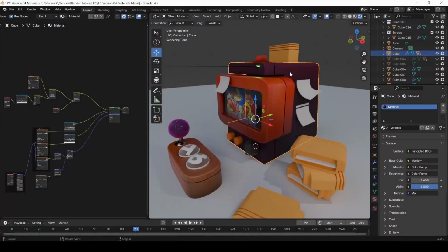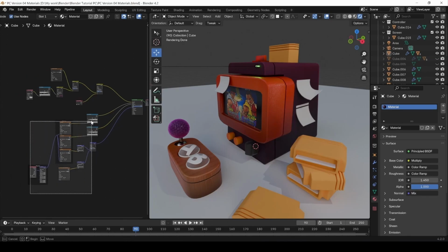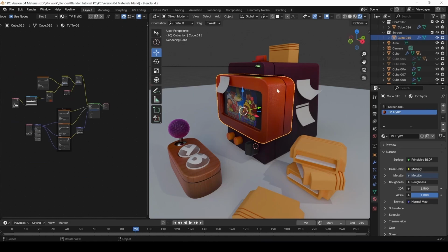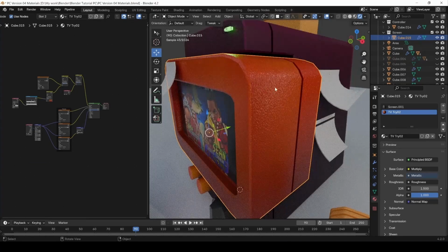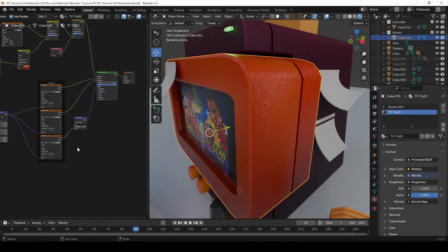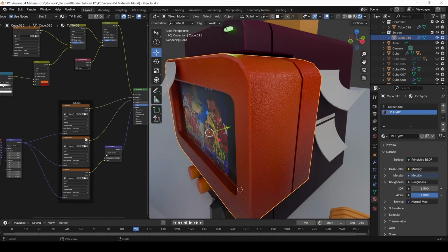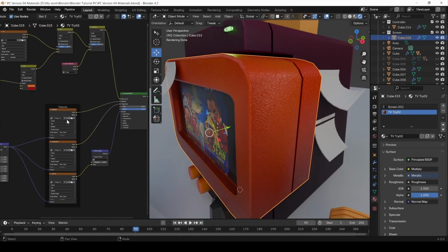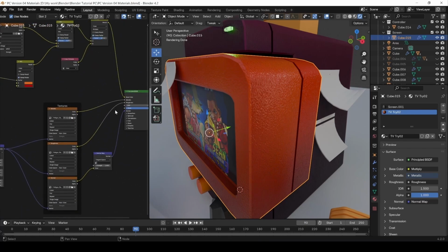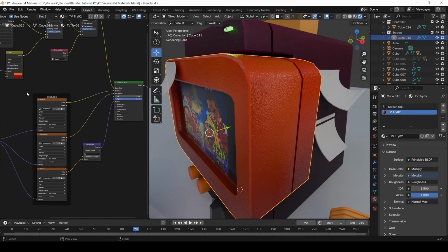So now we finished this, and what I decided to do is basically take all these materials, without this bottom one, I just copied them with Control C and took them to the others, to just have this effect here. Do you see it? It's the same as this one. I left the base color as it is, but I took the metallic and put it in metallic, roughness in roughness, and normal in normal. These three without any modification, just as they are.